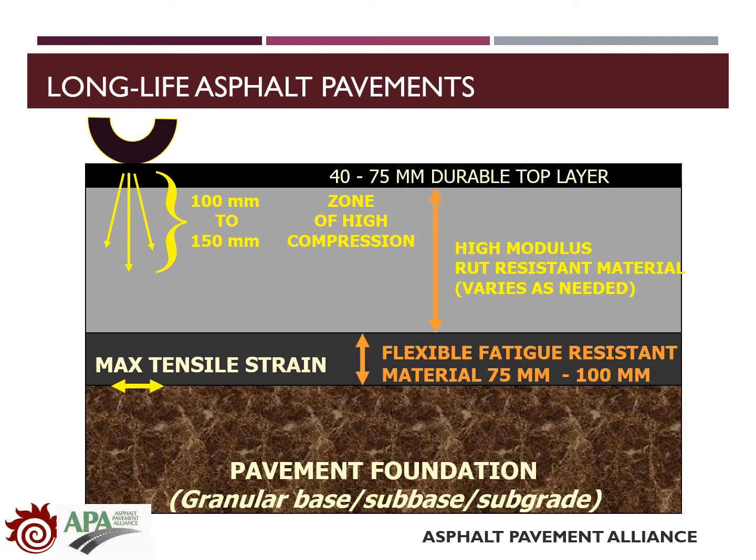For the top layer, we will introduce 40 to 75 millimeter durable materials, and at the middle layer, high modulus rut-resistant materials will be applied, and the depths will vary based on the traffic load applied to the pavement. And at the bottom layer, flexible fatigue-resistant materials will be applied. The depths will be around 75 to 100 millimeters.